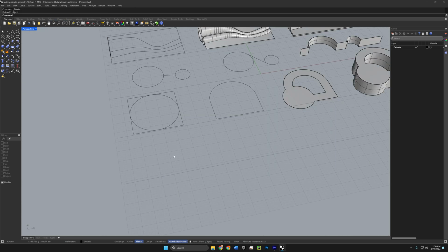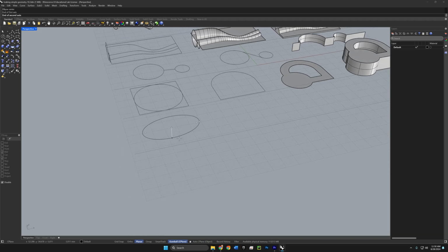Now we'll create an ellipse. And the submenu buttons for ellipse are quite similar to what we've looked at so far. So we'll just show how to make one vertical in order to cover something different. So by clicking on that main ellipse button there and then clicking vertical, we'll then be able to define the center of the ellipse. And I'll hold shift to make it so that this is aligned with the grid. And then we'll choose how tall we want the ellipse to be.